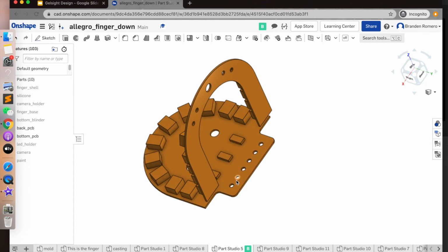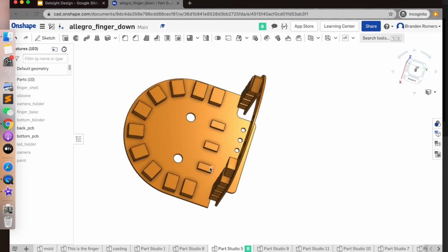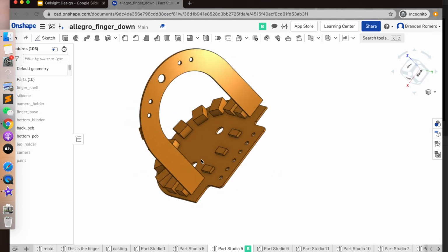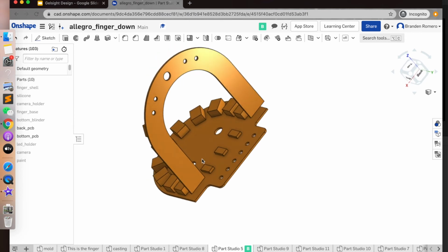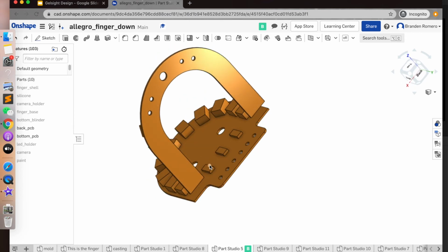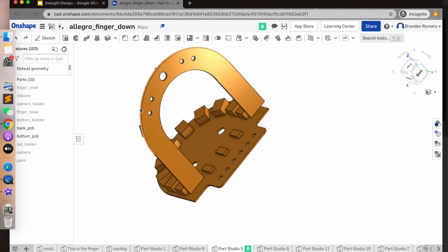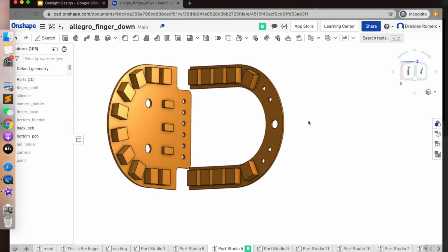We power it with 3.3 volts, so we have ground and power going into these. Then we have resistors, because each set of colors needs a different resistor value. Power comes in, goes through the resistor, comes to these pins, and these pins get connected to these over here. They each power one side of the LEDs.